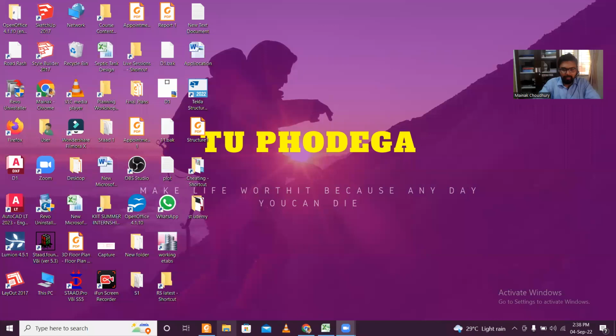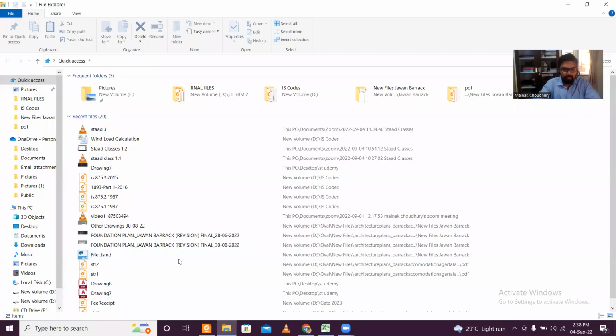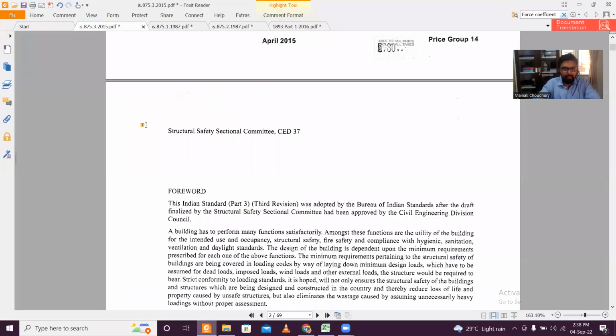So as we all know, the IS code for the wind load is IS 875 Part 3. Make sure that while you download the IS code, you get the latest version of the code, right? The latest version is IS 875 Part 3, 2015.